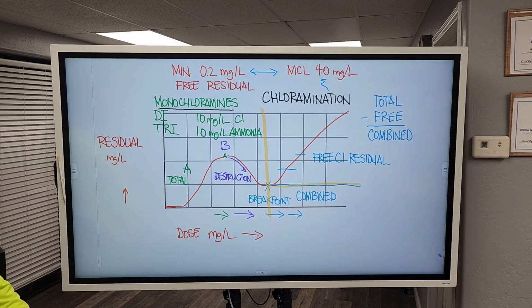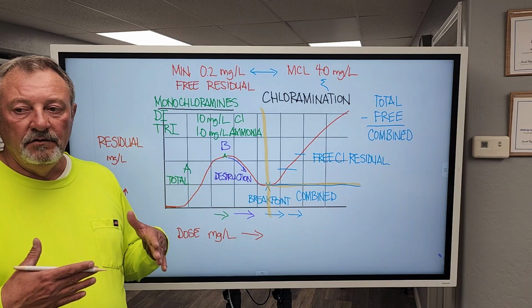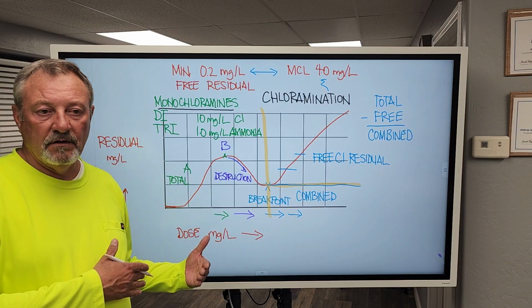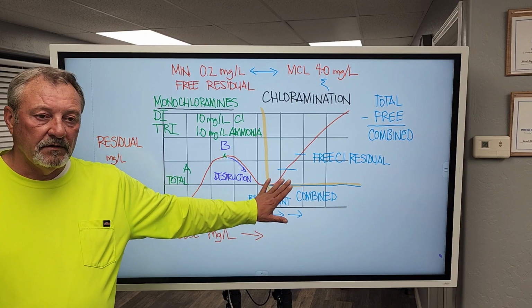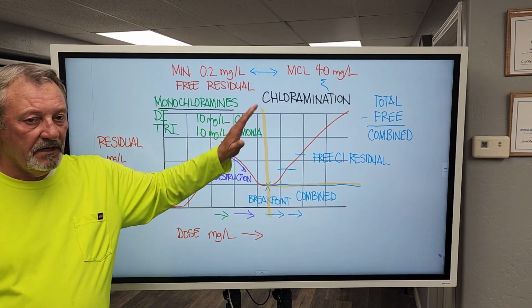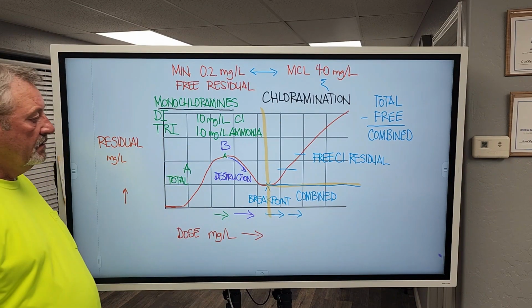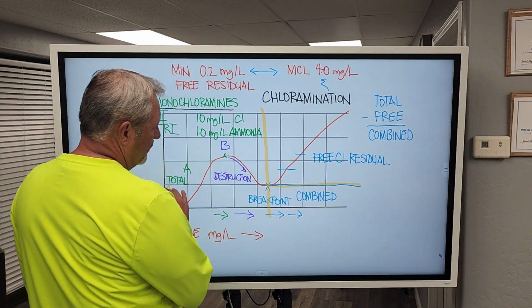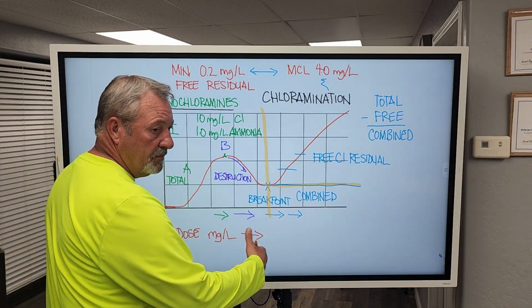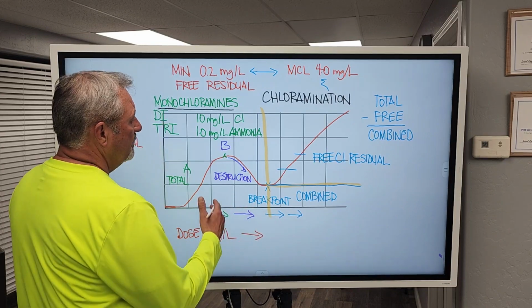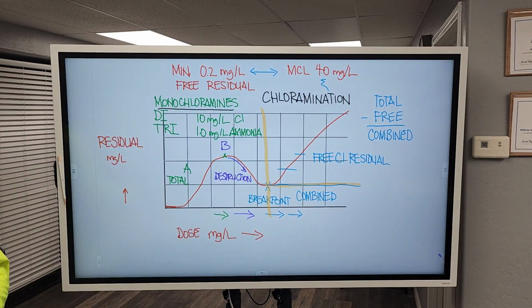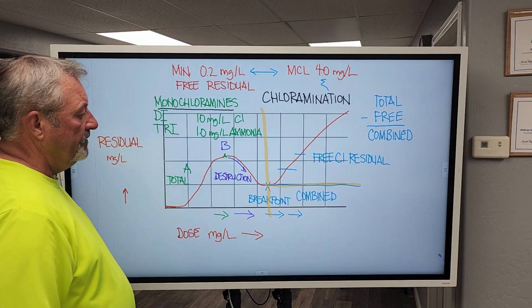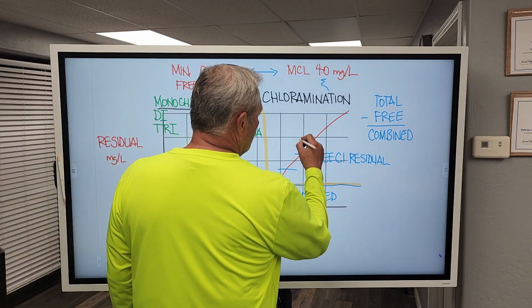How do we achieve chloramination? Well, it's different than breakpoint. A system can't use breakpoint in the morning and then switch over to chloramination at night. That's not the way it works. You're either practicing breakpoint chlorination or chloramination. And what happens is you'll go through the same process, increase the dose incrementally every 20 minutes or so until you achieve breakpoint and just past that.